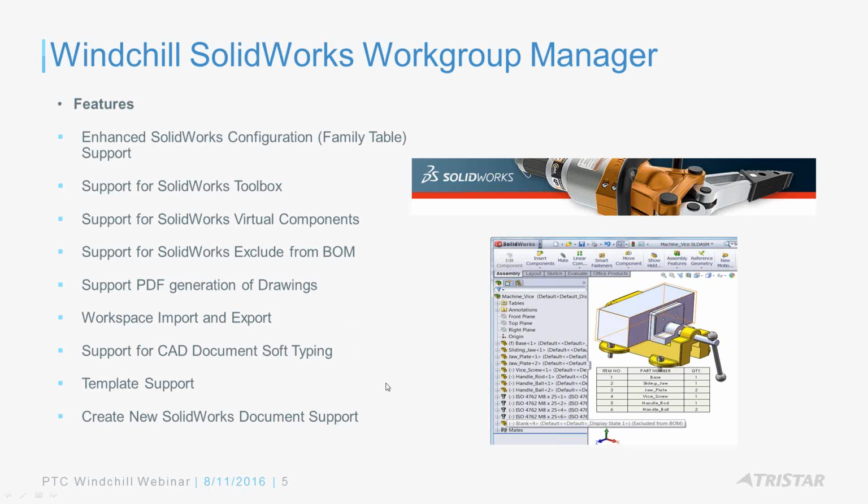And also support for creating and maintaining your SolidWorks templates in one location. So in SolidWorks, the user can access a common template managed by Windchill. So all the users can use the same start parts, drawing borders, and different templates that you define for materials, colors, BOM tables, things like that.